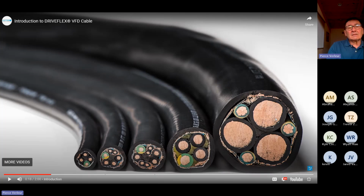That highly stranded cable also is very flexible, thus DriveFlex is the model name that Lutze uses, and several of the other VFD cable manufacturers use Flex in their names for their models. We used to call this welding cable. This is a very flexible cable. This is a pretty beefy piece of cable. If it was normal THHN, you couldn't bend it. But this one easily bends.